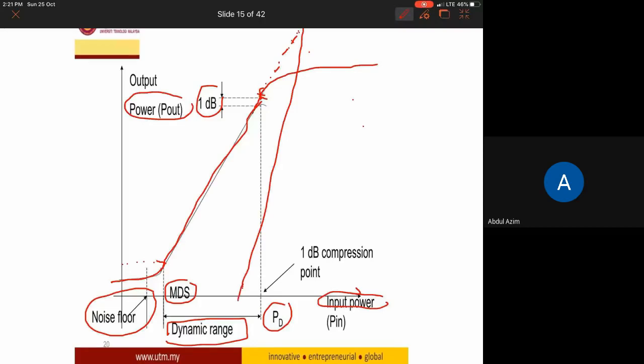So these are third order modes, output power of third order or 2-tone intercept point in dBm. So this is the first order, this normal one. This is the third order. At one point, this third order will meet at the top. This is another definition of what we call the IP3, the intercept point of third order. I will explain this later in the theoretical part.